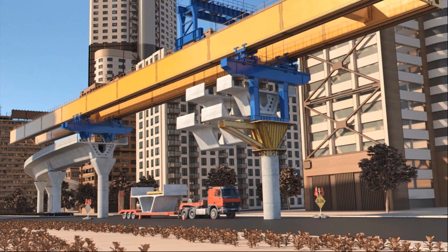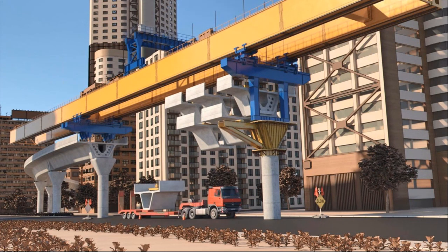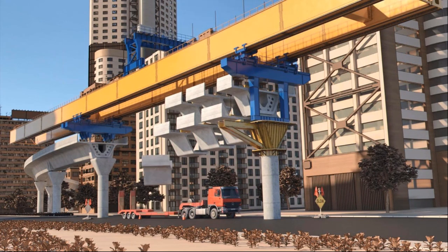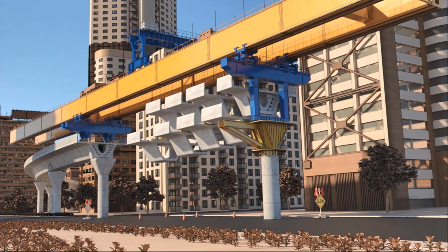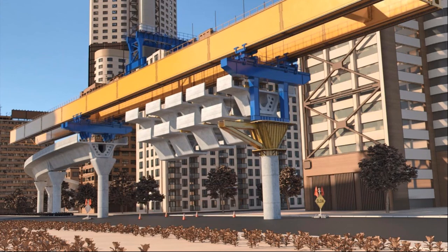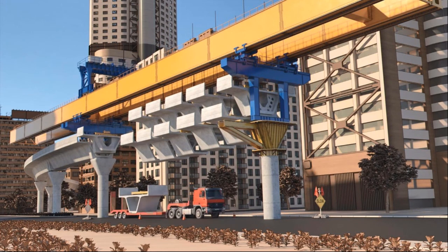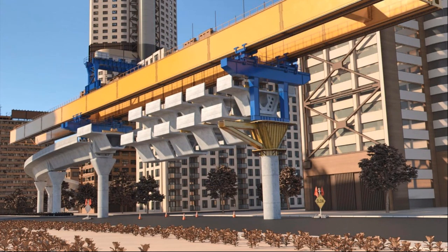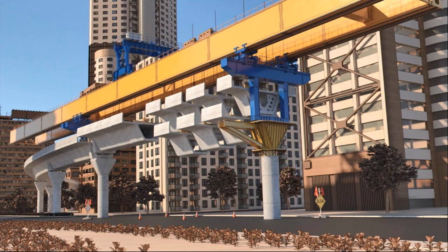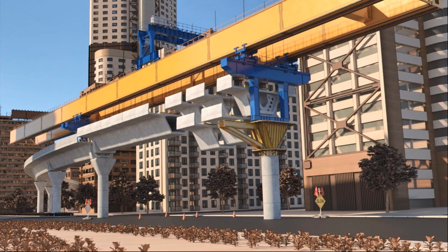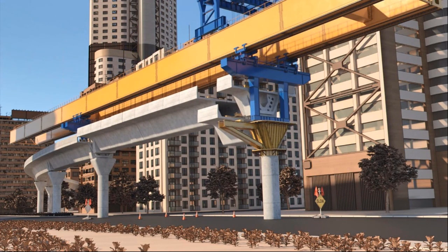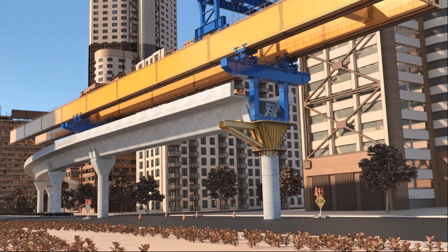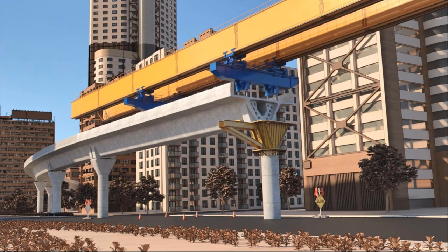You can see the gantry is going to hang all of the different segments for that span. And you can see it needs a little bit of room because these segments need to be put together one by one or pair by pair with the epoxy and the post-tensioning bars. So you want to get all of the segments hung, staggering them to create a little bit of space, and then start at one end with the pier segment and start attaching the segments one by one. So epoxy and PT together, epoxy and PT together, and then the last segment needs a little bit of room between where you're going to set it down and that front leg, and then the segment gets set down, tendons are stressed, and the gantry can advance forward to the next span. So that is a visualization of one way of that coming together.